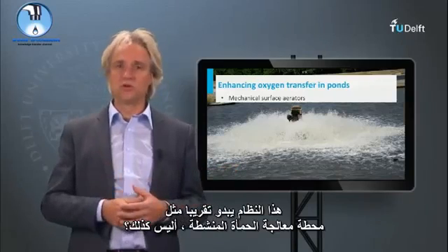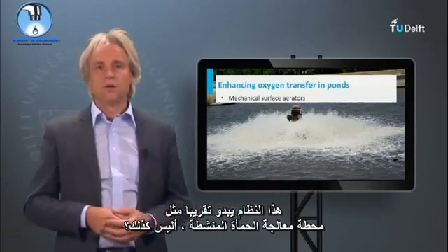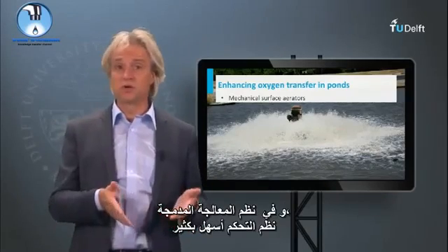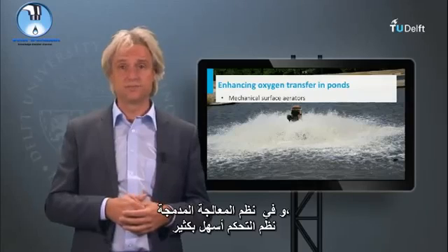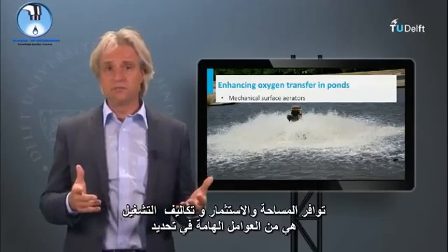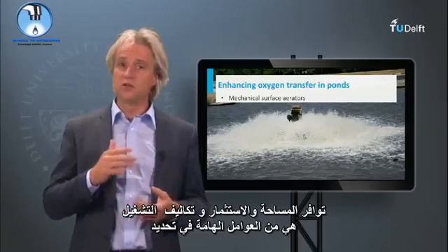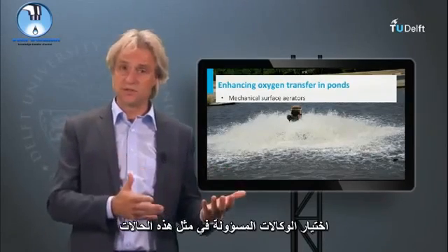This system almost looks like an activated sludge treatment plant, right? One can question if in such conditions we should proceed with pond systems. In a much more compact treatment system, system control is also much easier. Space availability, investments, and operational costs are important factors determining the choice of the responsible agencies in such situations.